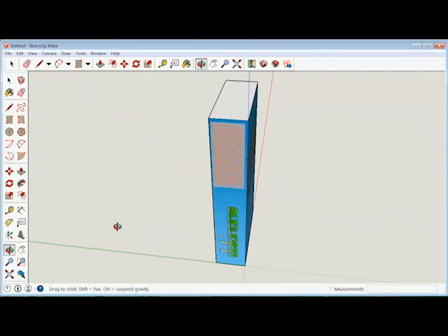And that's it. Our product has now been coated with our artwork and it's ready to be animated. So as you can see, we can scroll around this and it looks really good. The key, again, as I keep saying, is making sure that the measurements of your images exactly line up to the size of the object you're creating. If you're out, then you're going to get slightly repeated patterns, and that can actually make things not as polished as you'd like them to be. So now we're going to move on to animating this object and exporting that video file.